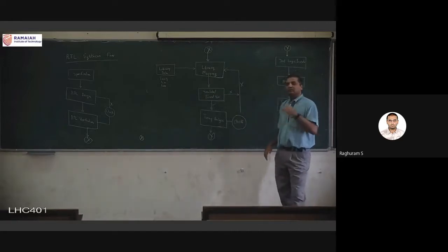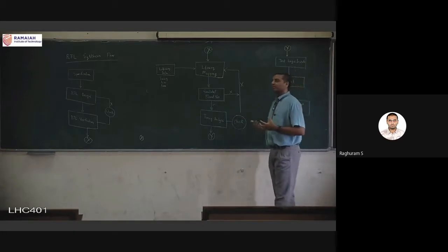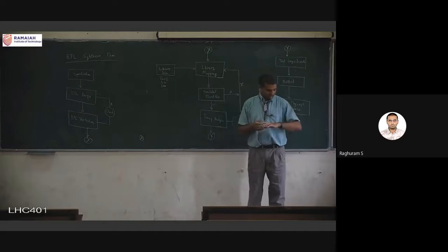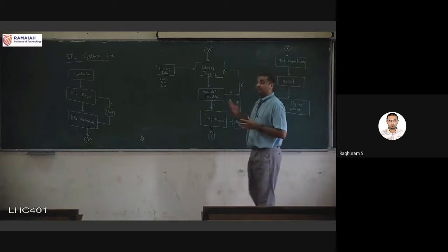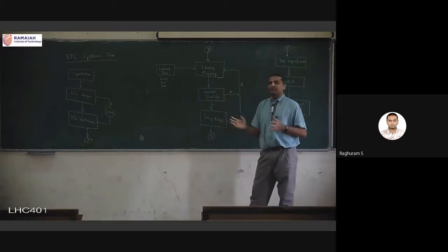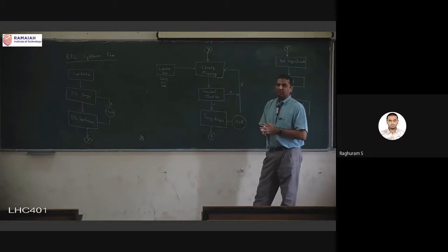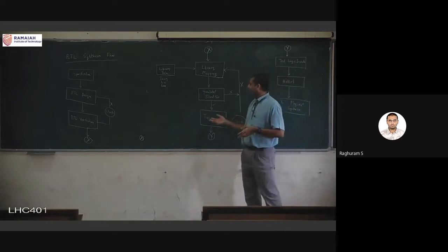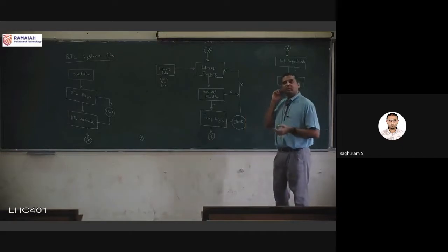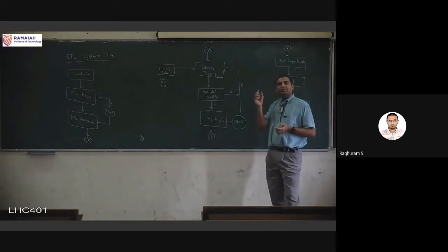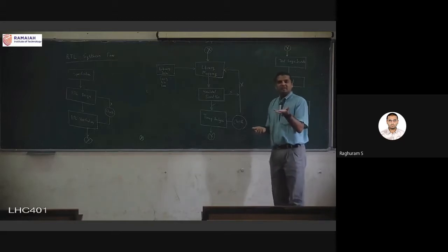And the reason for giving it particular values is certain types of fabrication errors. This is the main problem with VLSI design after fabrication. That is, now we are talking about post-silicon, what is called post-silicon verification. Obviously, some new things in terms of timing we can do again. But in post-silicon verification, one very important thing is, do some particular gates, or some part of the circuit, have a fabrication error? We want to correct that also, because now I have the actual silicon implementation.